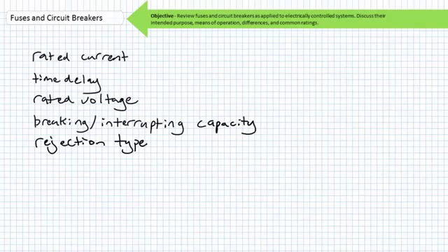The delayed action of a slow blow fuse is a heat transfer relationship between current and time. The higher the current, the faster the fuse will blow. The lower the current, the slower the fuse will blow. Ideally, the inrush current for a motor and a properly sized time delay fuse will be quick enough to prevent the time delay fuse from blowing. Correct fuse sizing prevents unnecessary disruption under normal operating circumstances.